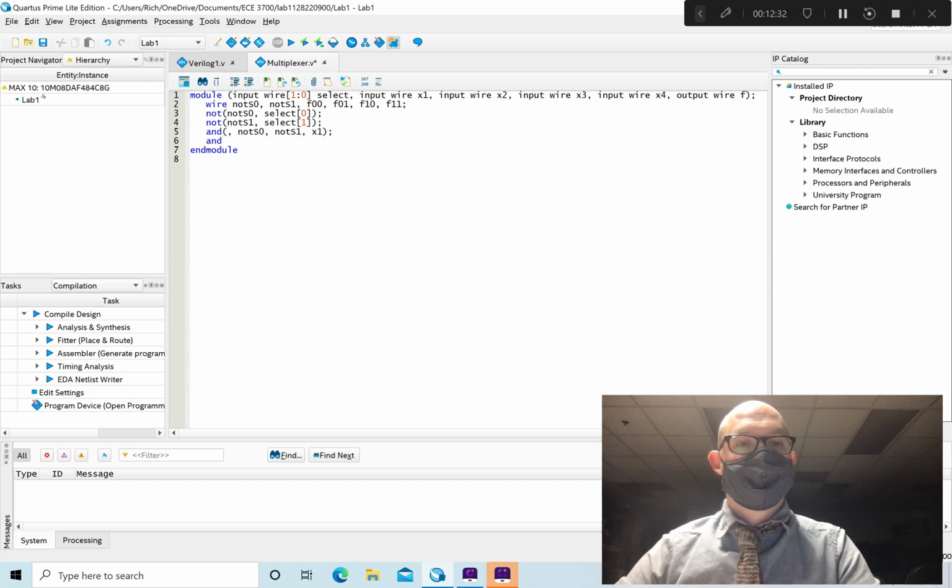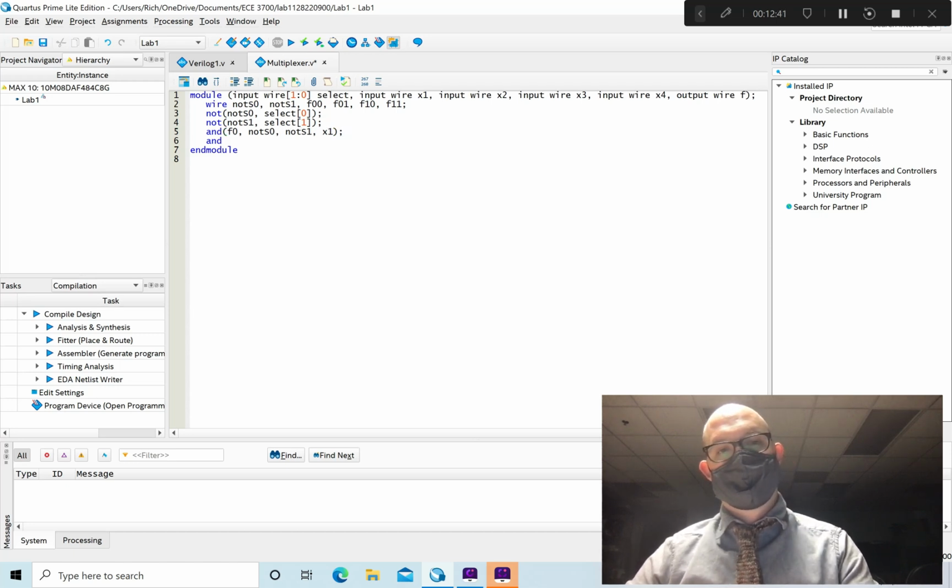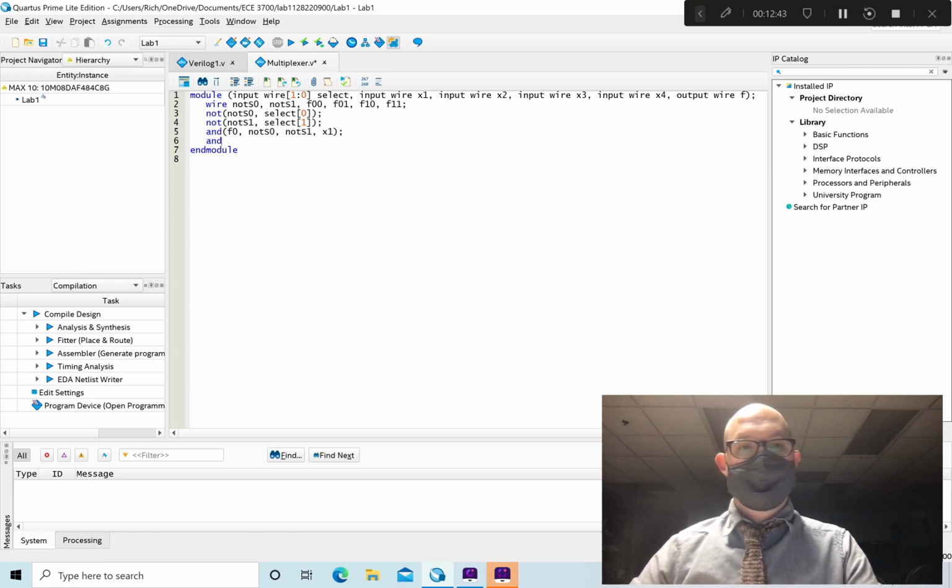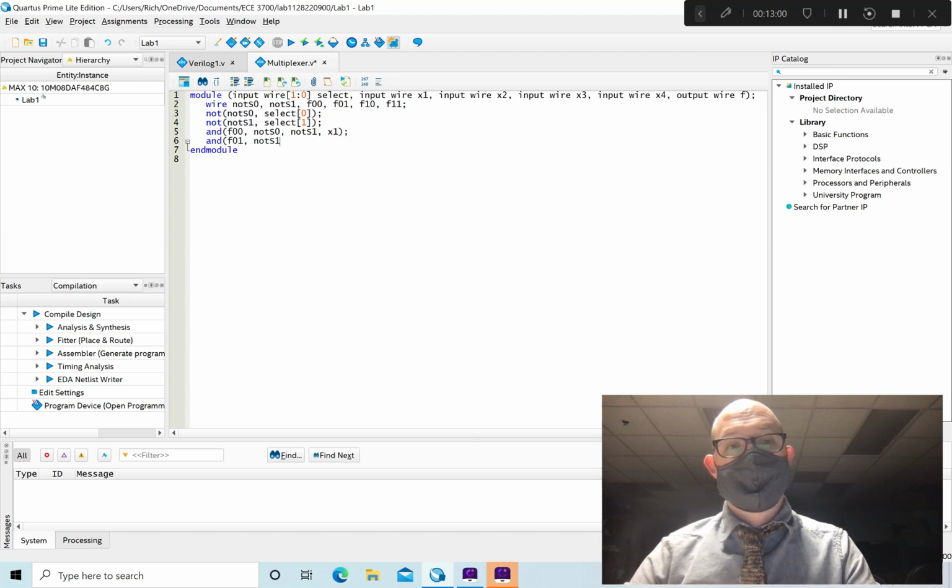Now I can put AND and call F0 the ANDing of not S0, not S1, and X1. And then I can do the same thing here. I'll say F00, I guess is what I said that was, F00. So then I can call this one, F01, the ANDing of not S1 and select 0.